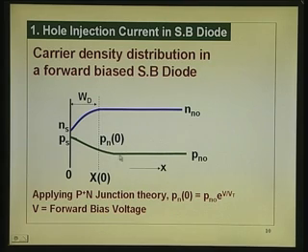The hole concentration will be changing like that, it will go up. When the depletion region goes up a little bit, it is still a small quantity. So, just at the boundary, you will have the hole concentration raised above p-n0, like in the p-n junction. When you forward bias a p-n junction, the hole concentration at the depletion layer boundary goes up from p-n0, from this value slightly up, p-n0 within the bracket at x equal to 0. And the value of hole concentration here from the simple p-n junction theory can still be written, whatever the voltage appearing across the depletion layer, it is by that quantity that it goes up. That is the law of the junction. Same law we are using here.